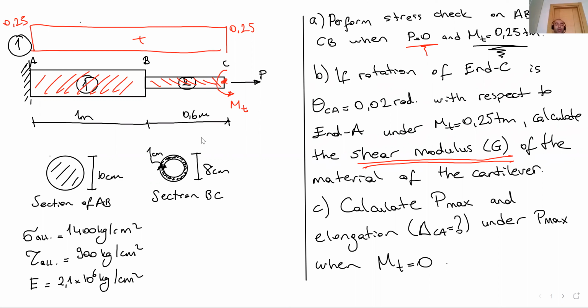That's okay. But if we are talking about the total capacity of the section, the minimum one is the capacity of that member. So we have to find the minimum area, because the force is stress times area.